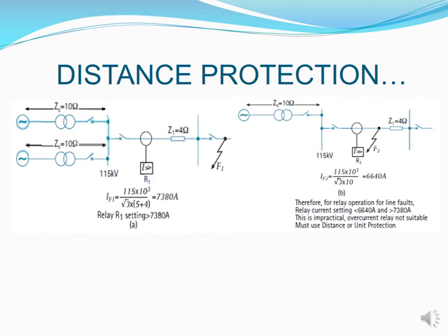In a situation like this, you'd either utilize your unit protection, where you look at the transformers as a unit and you look at that line as a unit as well, or you can utilize the distance protection, which is what we're about to discuss further into this lesson.